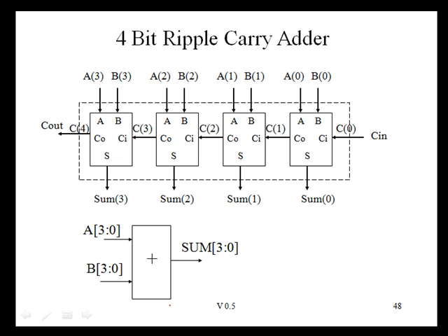We can use various combinations of full adder circuits to build binary adders that add two n-bit numbers together. This particular adder right here is going to add two 4-bit numbers together. This particular configuration of full adder circuits is called a ripple carry adder, in which we simply use one full adder for each bit that we're adding, and the carry out of one full adder becomes the carry in of the next full adder. It's called a ripple adder because the carry sequentially ripples through these adders. This happens to be the slowest form of an adder, but it happens to use the fewest number of transistors.